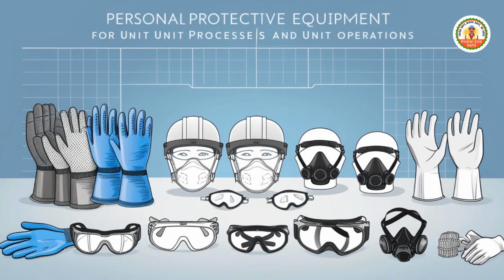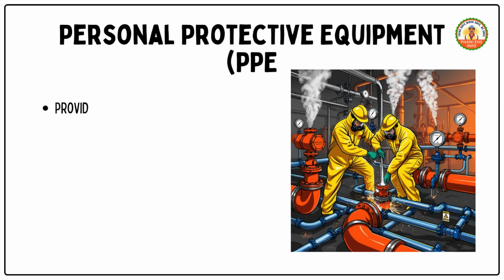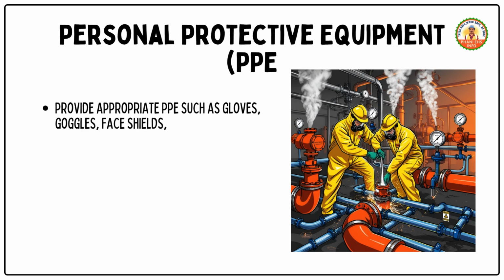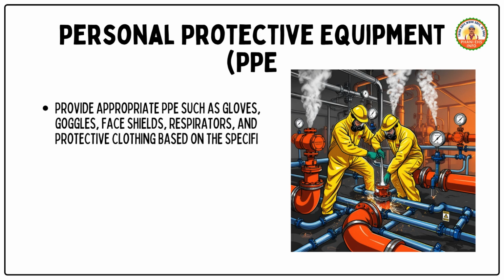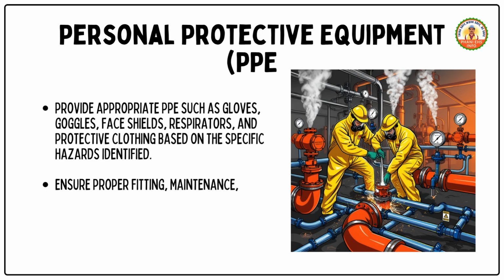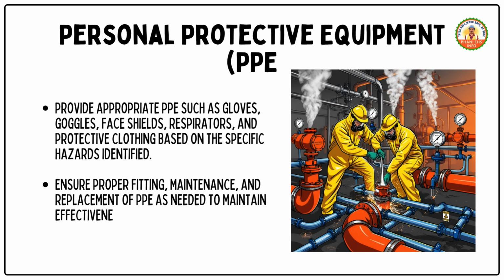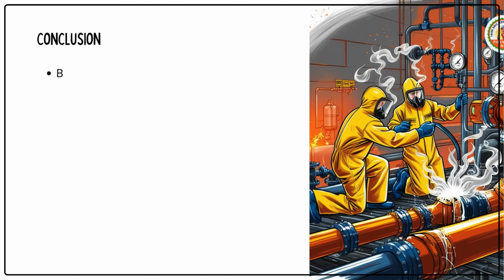Personal protective equipment, PPE. Provide appropriate PPE such as gloves, goggles, face shields, respirators, and protective clothing based on the specific hazards identified. Ensure proper fitting, maintenance, and replacement of PPE as needed to maintain effectiveness.